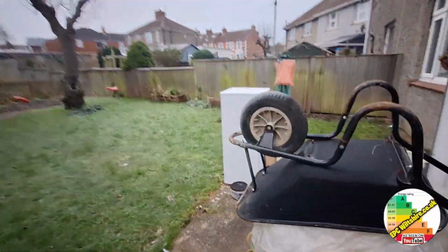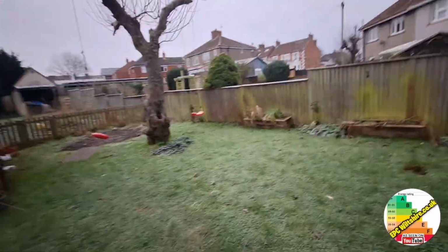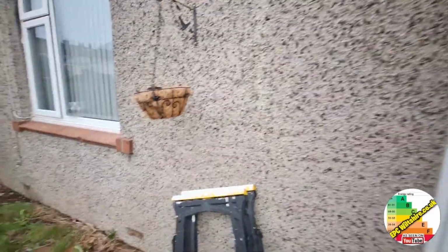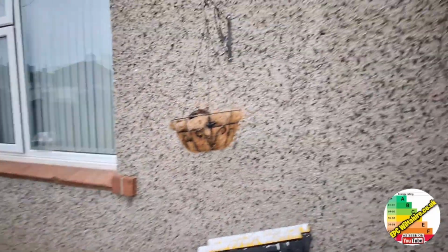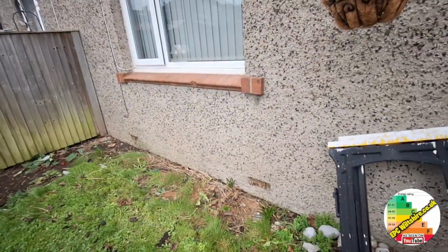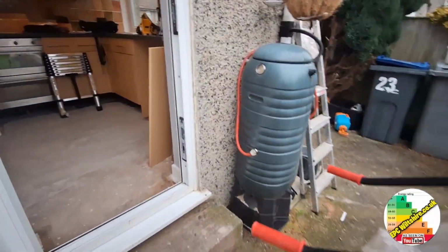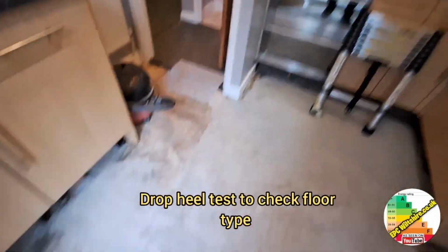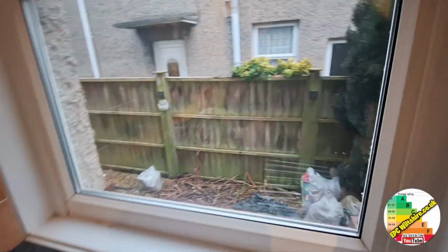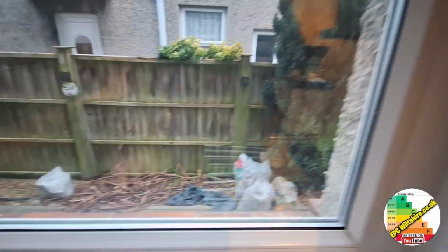The rear elevation, where the access door for the property is, here. Also, I've looked here for any drill holes, and I don't see any evident, especially under the windows as well. Not really seeing it, but more air vents. Suspended non-timber then, it looks like. Right, windows. So here we have some double glazing, UPVC.